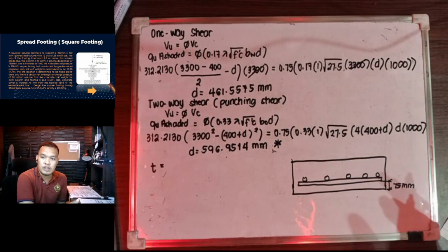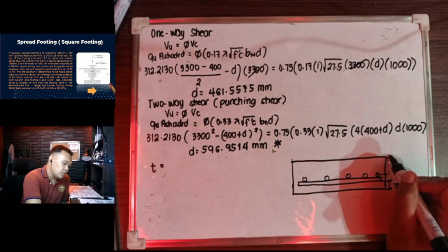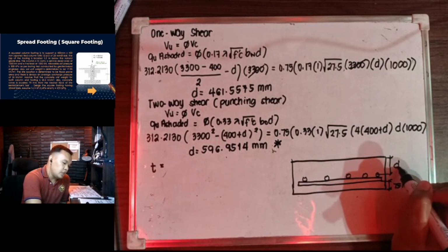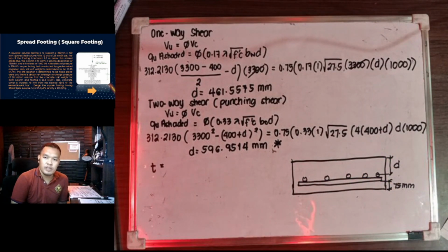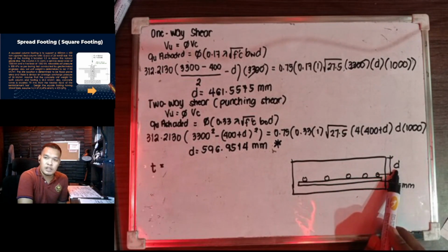But, kung nadaanan nyo to sa reinforced concrete design, no, the effective depth, which is the D, is located from the center ng bakal, no? So, ito yon, center nito papunta dito. Ito yung D. Okay? So, we have here yung center ng top bar papunta dun sa natin, we could have this effective depth, no?